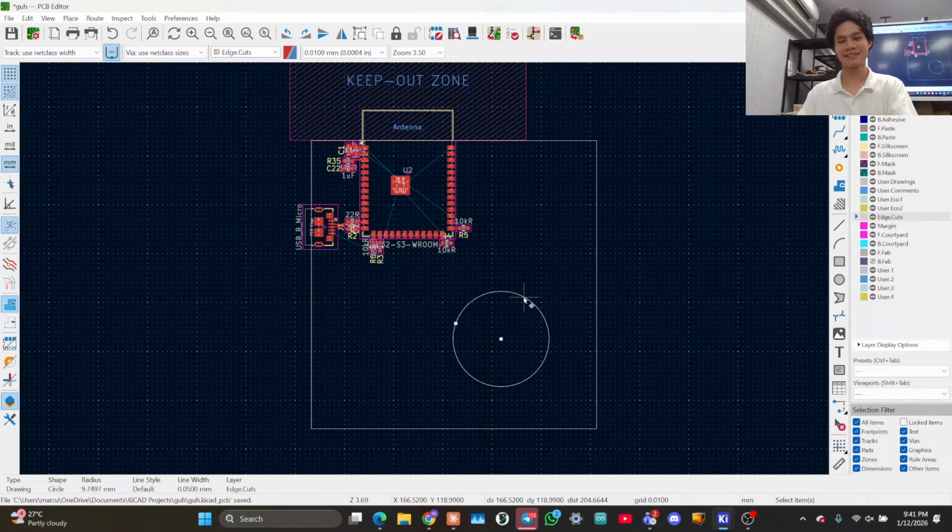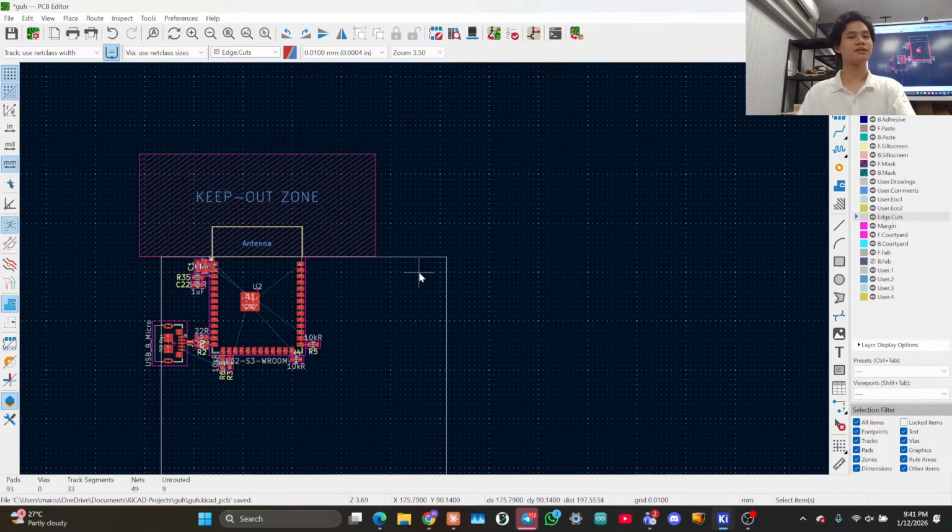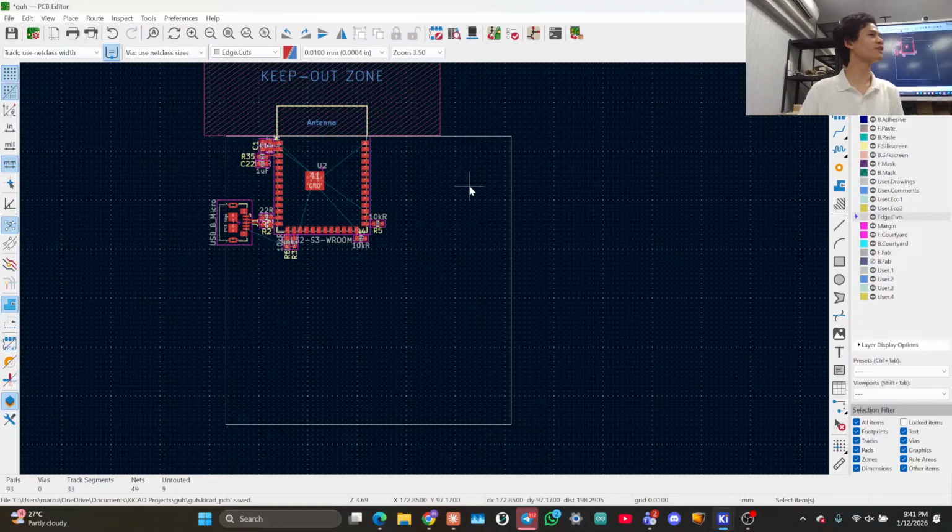So, fillet your corner, you don't draw the rectangle. Fine. I'll fillet the corner. That's the center of the corner. Put the center inside, yeah. Like this? Then I'm supposed to do this? This is such a painful way to fillet things. Like that, yeah. Snap to 90, but you cannot use rectangle, you have to use line. Then just line plus the two radius. Alright, so basically it's too much effort to fillet the board.